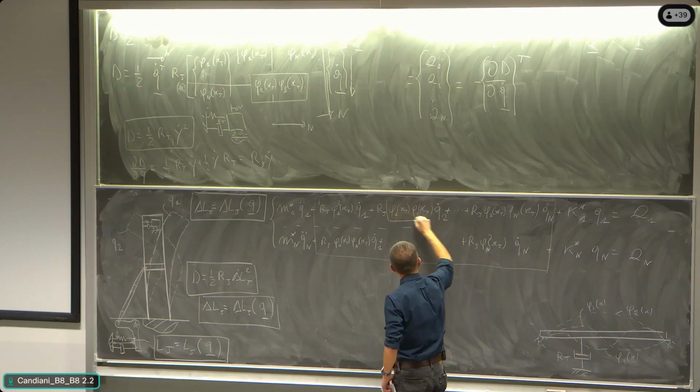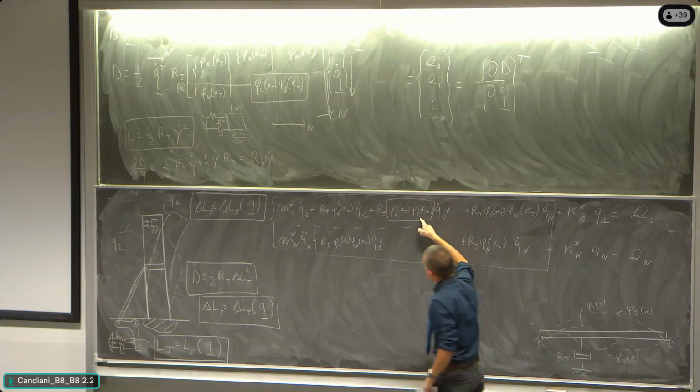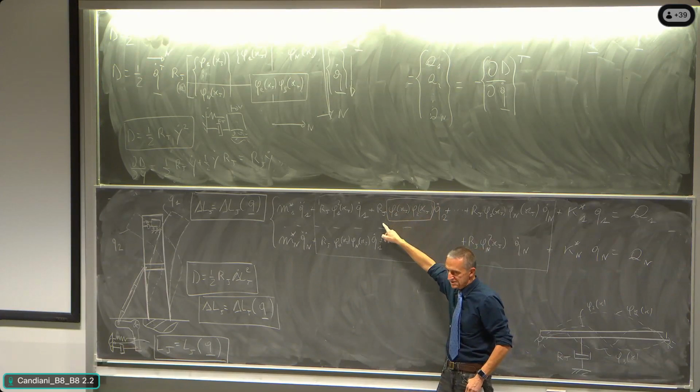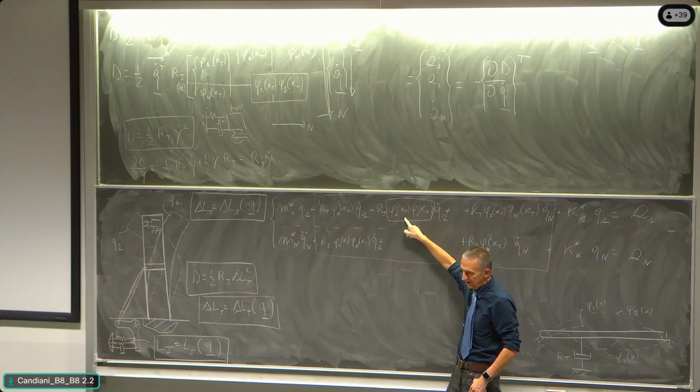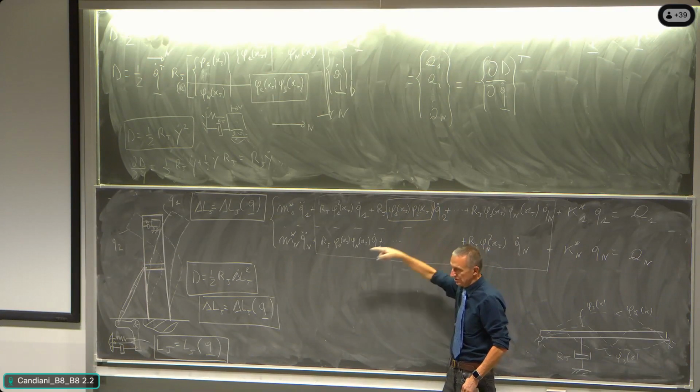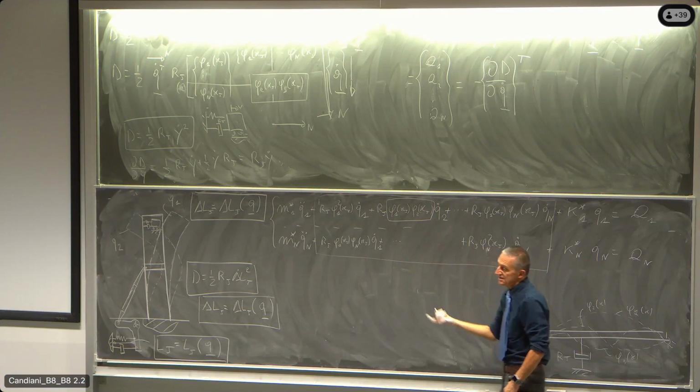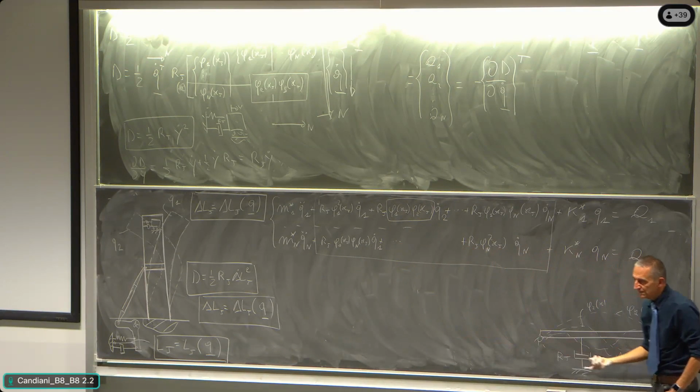Those quantities are saying that the damper itself is effective, but just in case the location where it is positioning the force is not a nodal position.